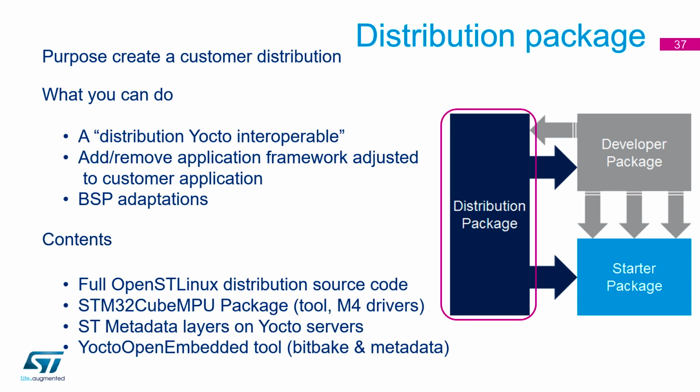And then when you want to generate your distribution package, we have that one. It's all done with Yocto in our case, so we've run all the Yocto tools on it. You can run whatever bitbake and all the Yocto recipes that you need to generate your end application and the distribution package. So your distribution package will then generate a nice new developer package and a nice new starter package for you when you run that.